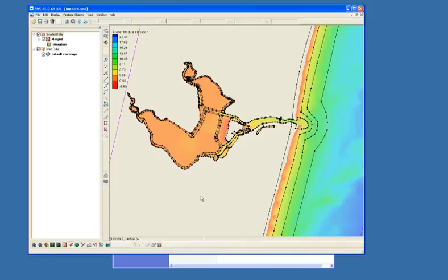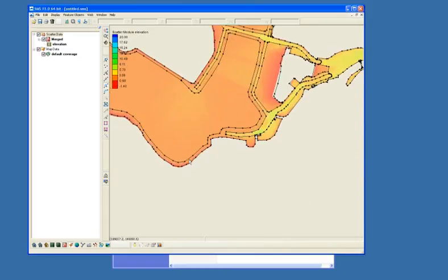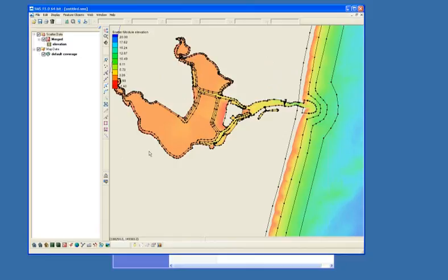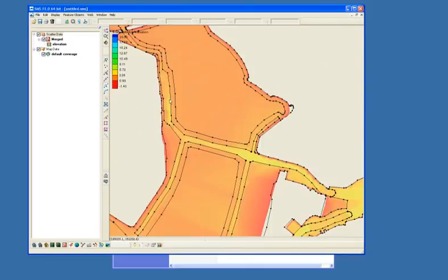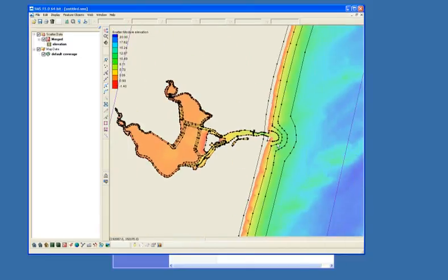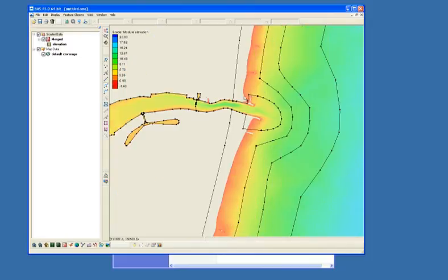And this is one that's closer to what we used for this actual project, but it's not exactly what we used. But you see how we went around the outside where we had the land specified. Just inside from that we have another zone. It's pretty flat in this area. We don't necessarily need any more. So there's a lot of different areas here that we've created. You see that we've increased the resolution across where the ebb jet's coming out, where the ebb shoal is.